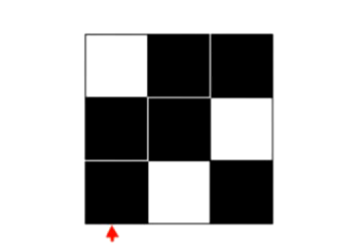Find the first warp yarn and follow the path of this yarn. It's obvious that there are 2 warp risers followed by 1 warp sinker per repeat. Follow the second warp yarn and you can see that the warp sinker is first, followed by 2 warp risers. The final warp yarn in the repeat has a warp riser, a warp sinker, and another warp riser. The pattern is repeated in both the vertical and horizontal directions.